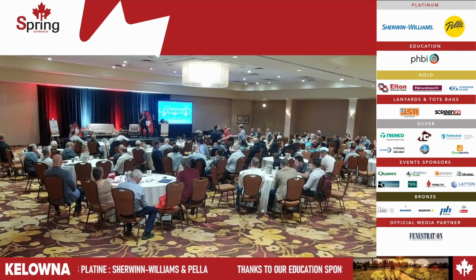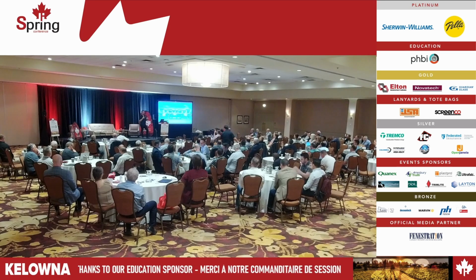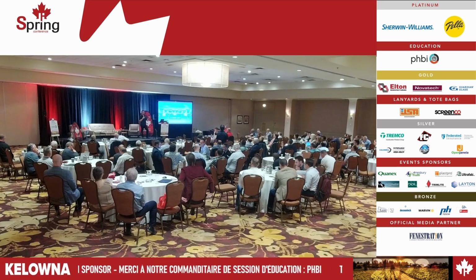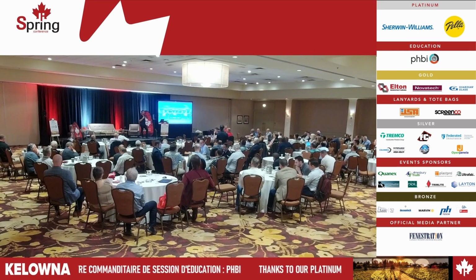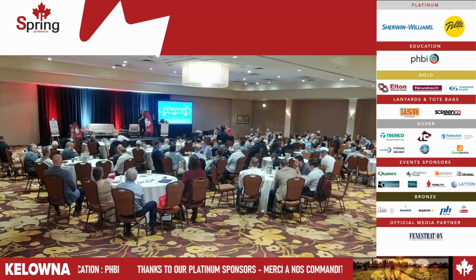100%, and also direction of orientation. So the window and door to wall ratio, windows are your weakest link in any project. So orientation, like we reviewed in that one case with what they're facing, dramatically affects the step code metric. So if we are having a project that has very high window and door to wall ratio, oftentimes we're having to spec triple glazing in order to hit the step code requirements there too.